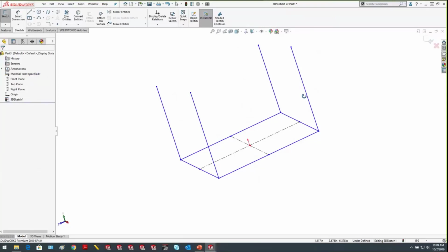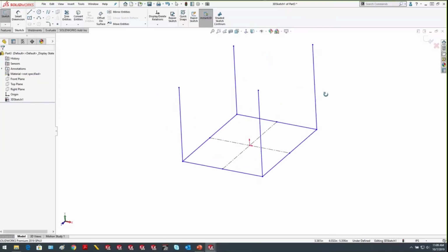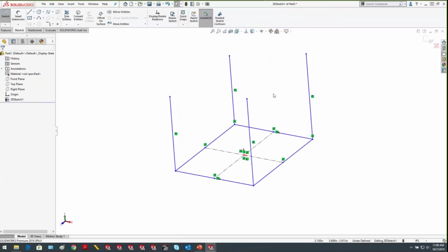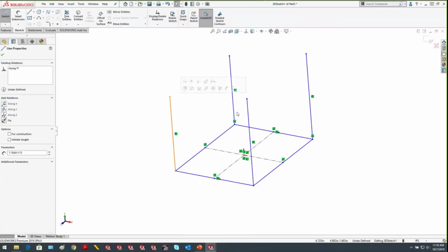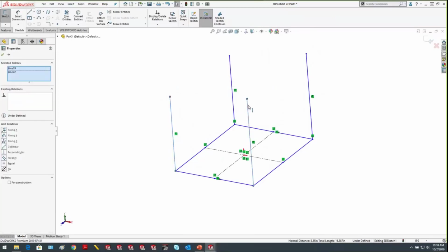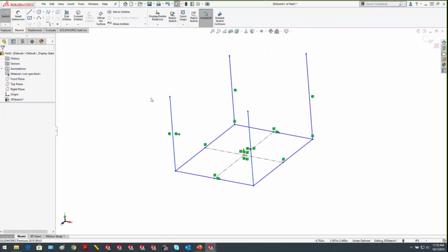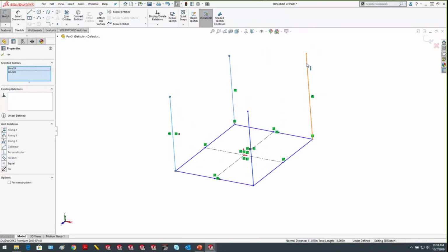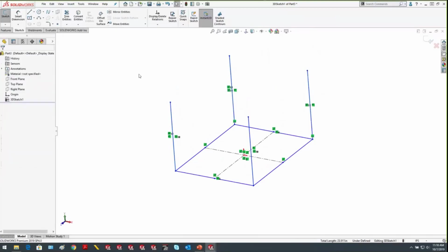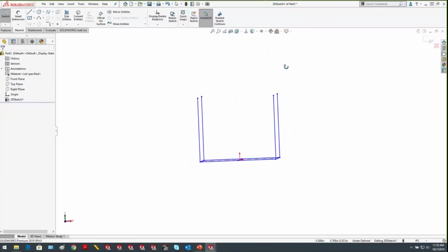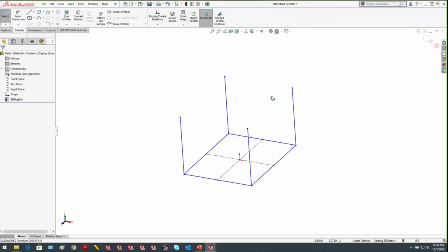So in this case, I snapped 4 lines directly on the y-axis, and we also have access to our traditional relations in a 3D sketch as well. So if I wanted to control select both of these lines and make them equal, I can still do that in a 3D sketch. So I'll go ahead and select the rest of the lines also and make them equal. And you can start to see my 3D cube is taking shape in my 3D sketch.